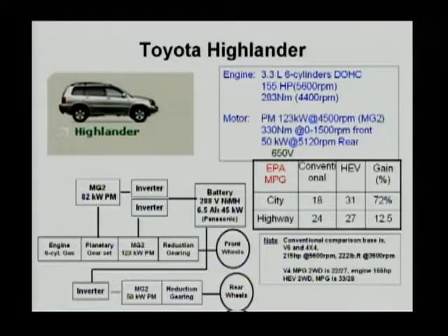So simply, they have more battery cells connected in series to form 288 volts. Each of the nickel metal hydride battery cells is 1.2 volts. They put 6 cells together to form a module, which is 7.2 volts for each module. In the Prius, they have 28 modules in series. In this one, they have 34 in series.